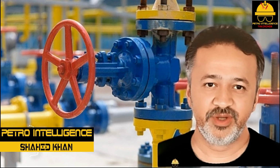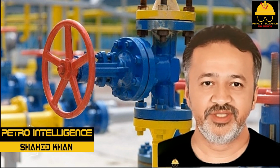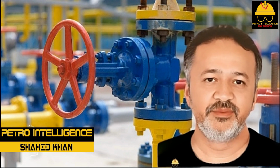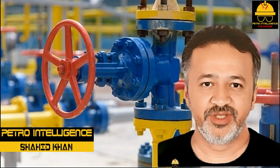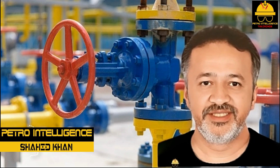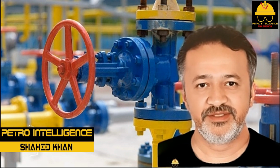Check valves operate by gravity and must be installed correctly. Ball, lift, swing, and stop checks come in horizontal and vertical designs. Check valves are designed to be used in a variety of process conditions. The specific condition dictates the type of material the valve will be made of. For example, the stainless steel check valve is used on corrosive, high and low temperature services.